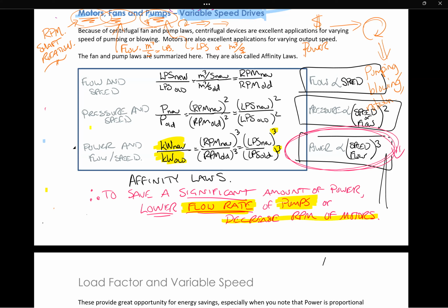Can we decrease the RPM of some motors? If the process is not a bottleneck, can we run some motors slowly because it's waiting for some other processes that are the bottlenecks? Can we decrease that RPM and get that significant change in the power required?